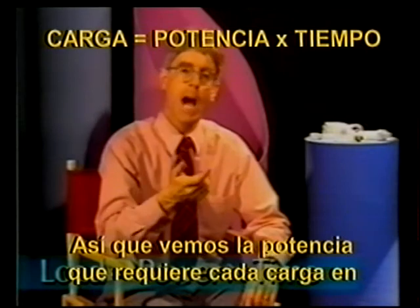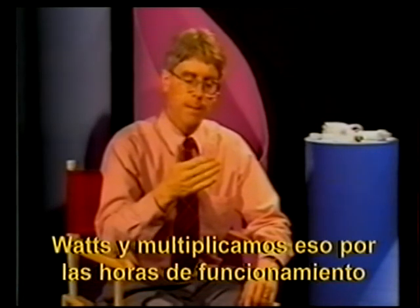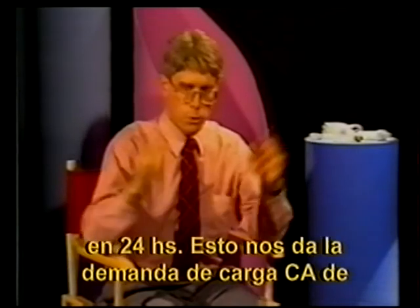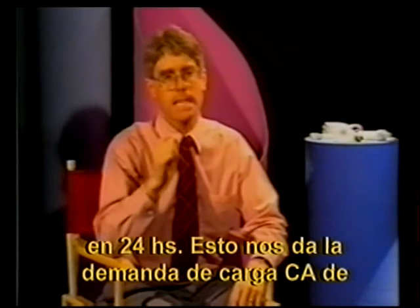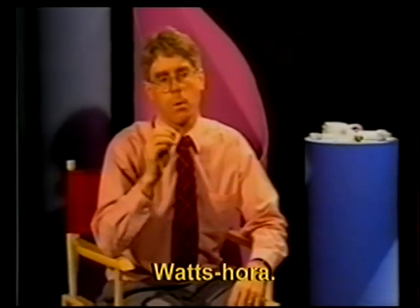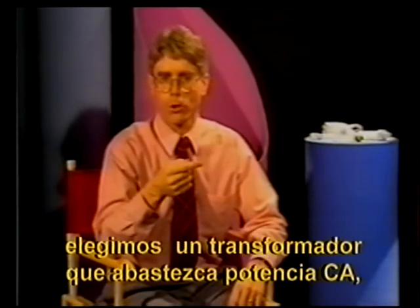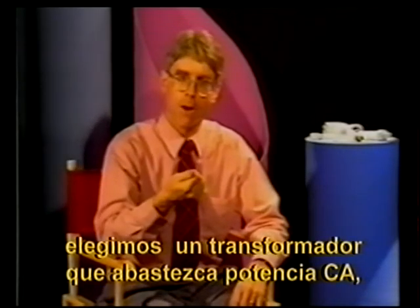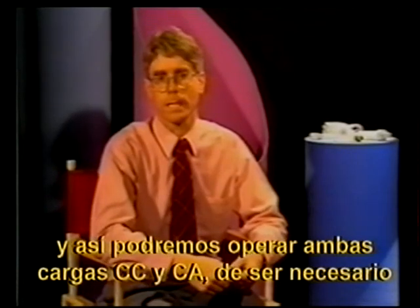So we look at the power that's required by each load in watts, and we multiply that by the hours of operation in 24 hours to give the watt-hour AC load demand. Once we have the AC load demand estimated, we will then choose an inverter that supplies AC power and be able to operate both AC and DC loads if we need to.